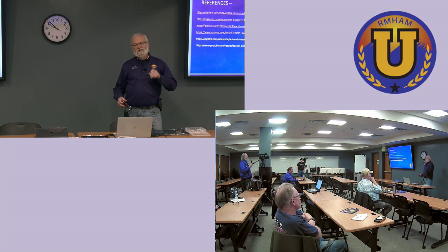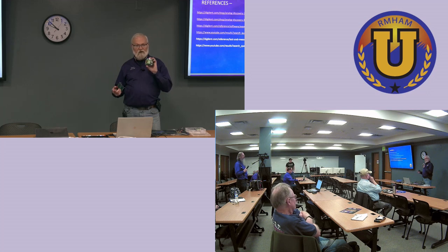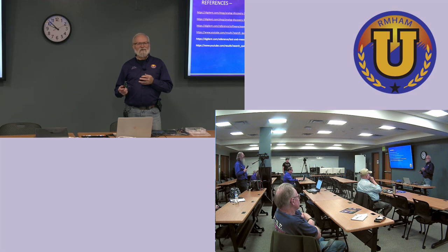The core of the module is an FPGA. So let's take, for example, if the logical I/O, the digital inputs and outputs, are wired directly to it, you don't want to go over 5 volts.